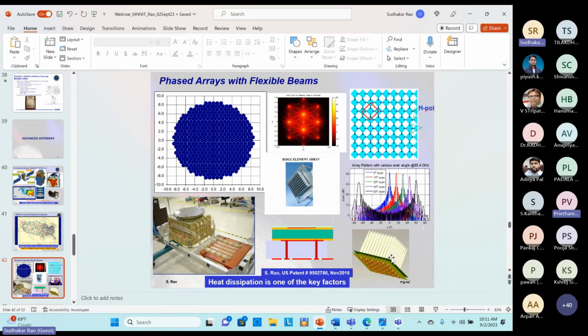Okay. In what way does it differ from the 5.8, the other types of Rogers, sir? Other types, it depends on what epsilon R you want. Rogers has so many, going up to epsilon R of 10 or even more. They're basically ceramic based, so I think it's expensive. But if you are going with Rogers, I think 4003 is highly used because it's cheaper as well. For university purposes, you can use FR4, which is commercially available and cheaper than Rogers. Okay, sir. I understand. Thank you, sir.